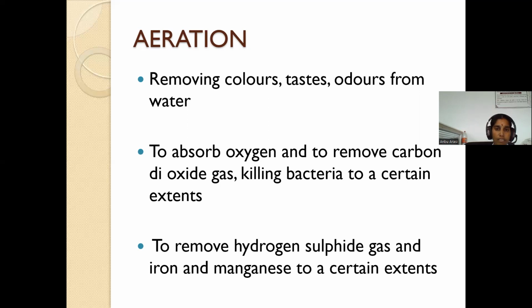Aeration is defined as the physical process in which water is made to contact with air in order to absorb oxygen and to remove carbon dioxide gas. This process also kills bacteria and removes hydrogen sulfide gas, iron, and manganese to some extent.